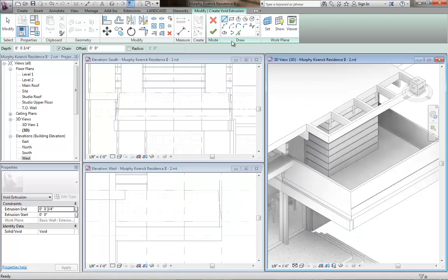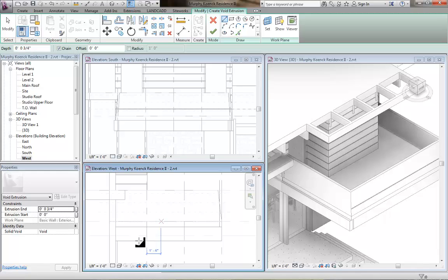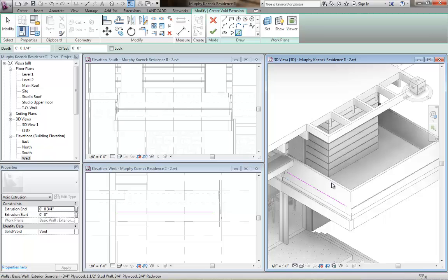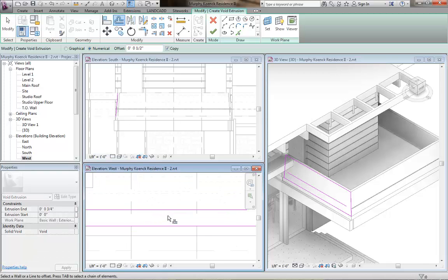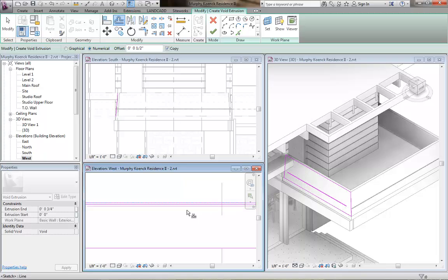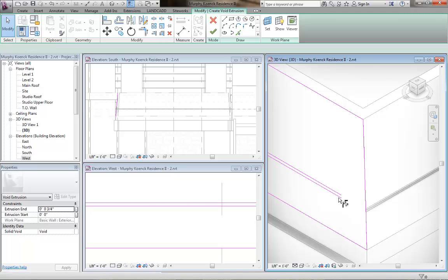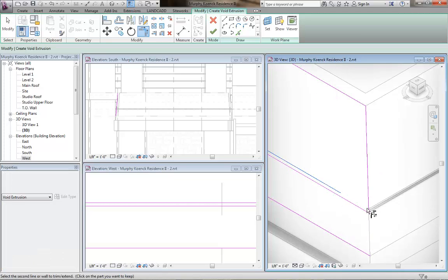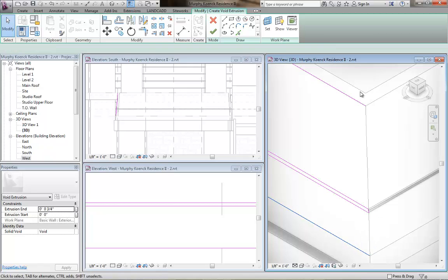Okay, let's unshow it, and then let's draw here a line. And again, we'll just draw it. And I will pick, like I did before, the face, get those edges, and then we'll offset this by 1/2 inch on each side. Get our 1 inch tall reveal. Okay, go ahead and delete this. And then let's trim this out. This is the tedium here. Okay, get rid of this line, get rid of this line.